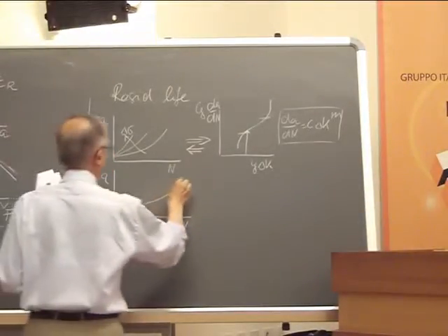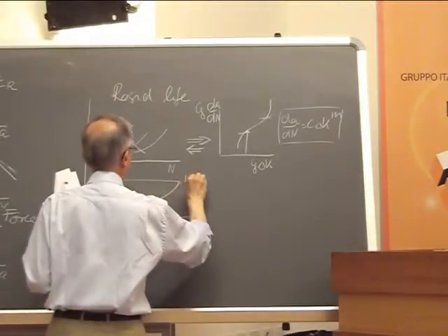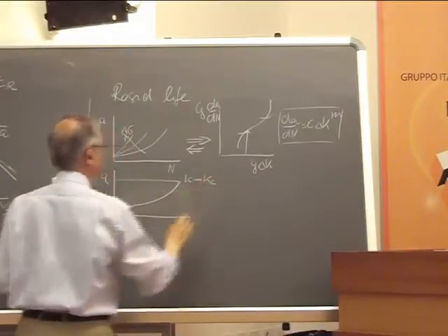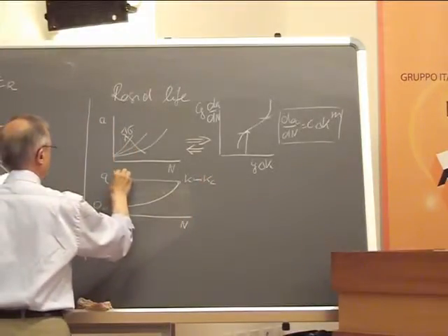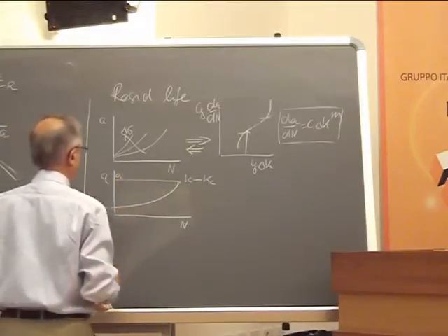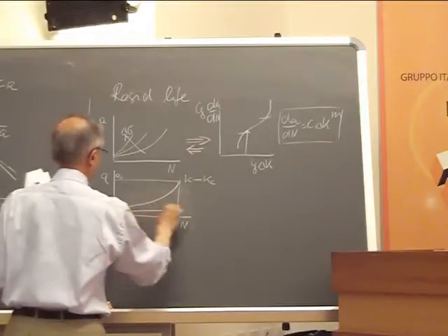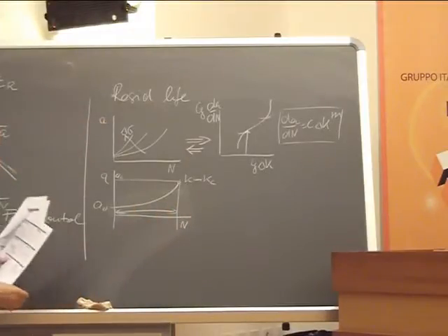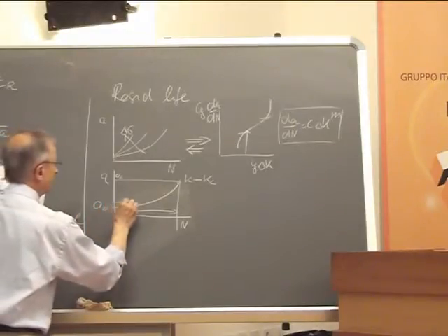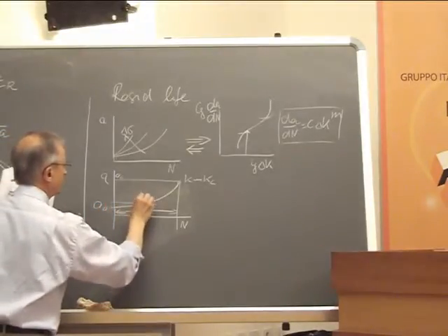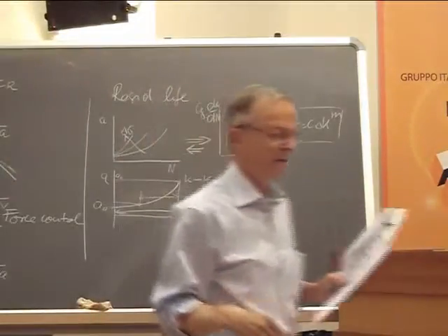and here is a failure point where K has reached Kc, so this is the limiting condition. And here we have a critical crack size, and so this is then the remaining lifetime. Or had we entered the diagram here, this would be the remaining lifetime. So you can play around with these things. It is very, very basic.